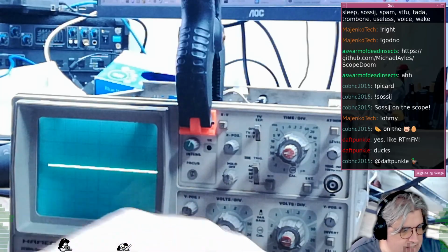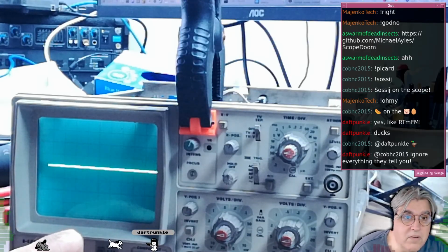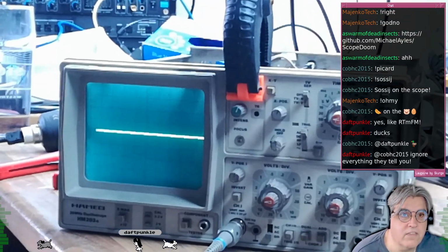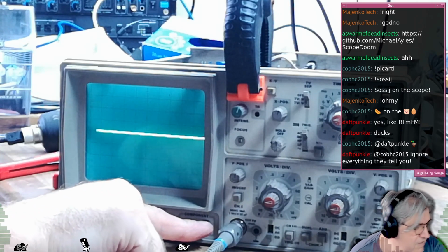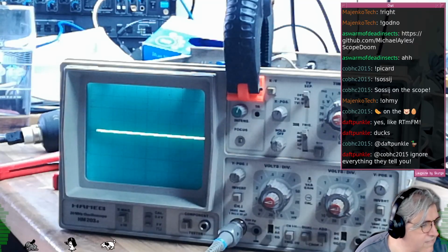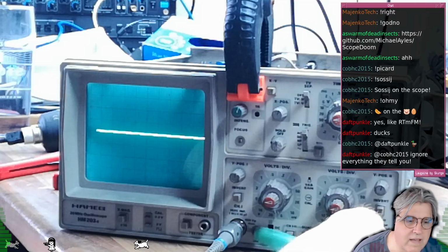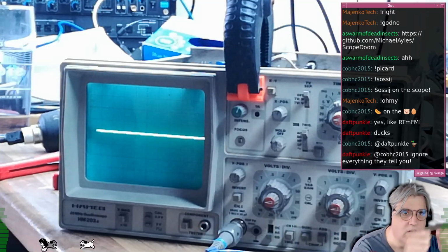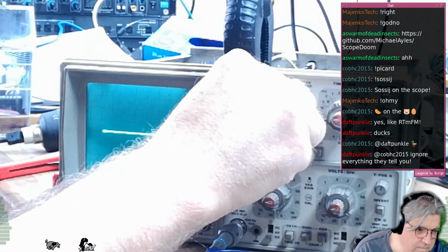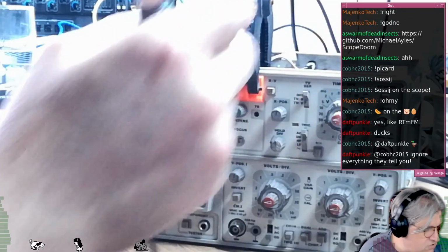Right, component tester. That is what we really want to play with. Well, that's what I really want to play with anyway. And that's the component tester down here. Let's lower this down again. The theory is you put a banana jack cable in there, a banana jack cable in, you can't see it because my hand's in the way, a banana jack cable in there, and a banana jack cable in there. That's a ground pin, that one. So from there to ground, and then you put your component in between the two, and this tells you whether the component's working or not, and various things about it. It's basically a rudimentary curve tracer.